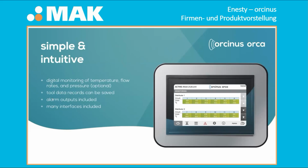So the alarm outputs give you the situation that if one of these turns red, then you will have an alarm output to the injection mold machine and the machine will stop, because anything you produce from now on would not be in perfect quality. So this gives you an insurance to always have perfect quality.